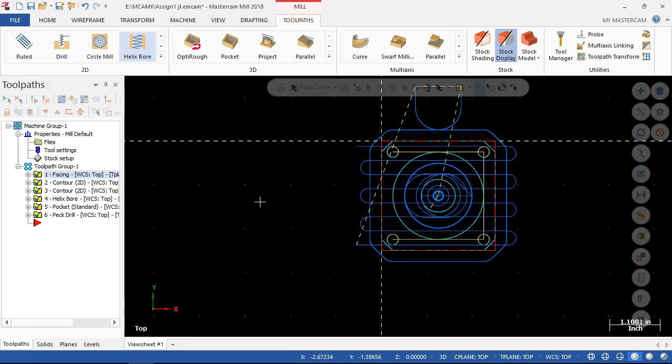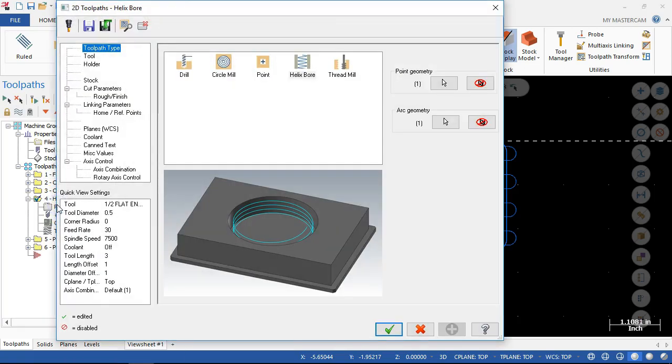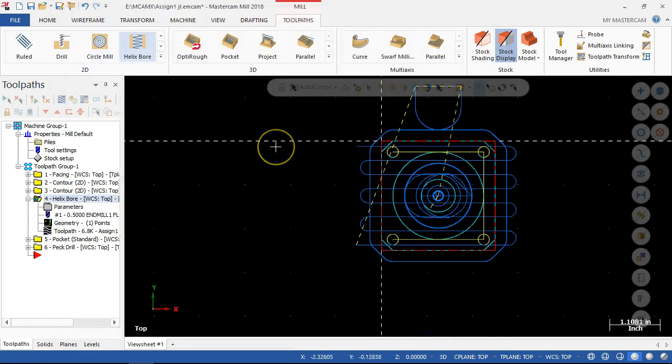True, but when you're doing the helical interpolation, you're generating a lot of lines of code. Right. I think you could just generate one and say loop it 10 times. Well, it depends on the pitch. And we're not telling it to do subprograms or loops at this point. So you do have the ability to. I think you can do the subprogram, but at the other end of that is the length of the program,